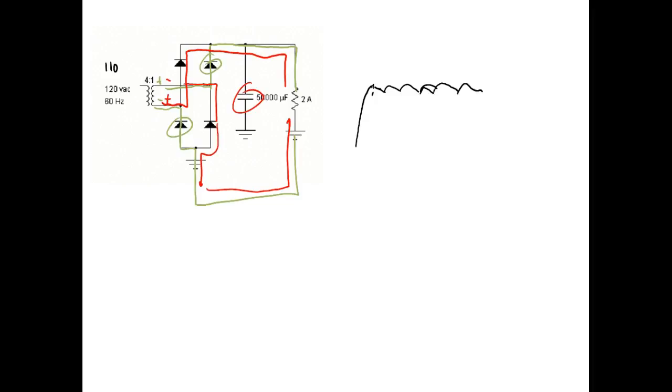But your voltages have to be within a tolerance of 120 volts. I think it's 10%, which is the maximum tolerance that the power company allows. So as long as we make sure we get that 10% out of the way, then our regulators will regulate.